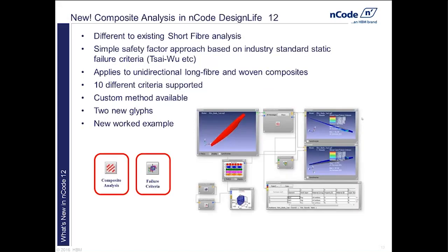So looking at composite analysis to begin with. So this is a new option in DesignLife at 12. So this is separate from the short fiber analysis that we've had in there for a while. This is looking at simple safety factor, static failure criteria analysis based on industry standard failure criteria. So not a fatigue calculation, but looking at static failure criteria.